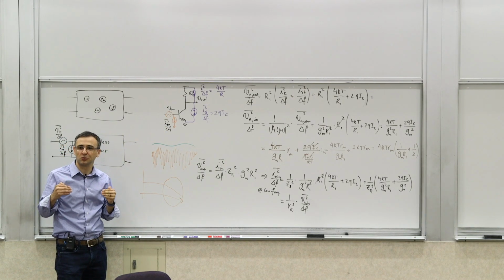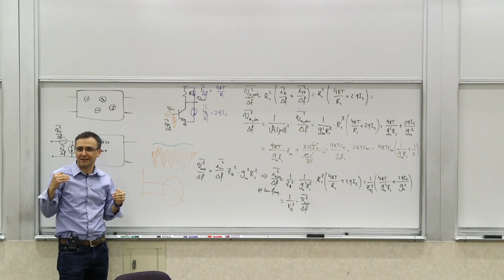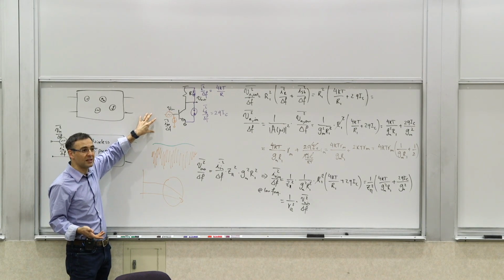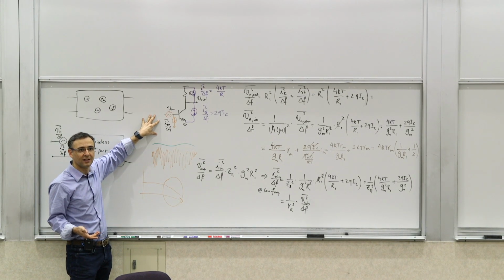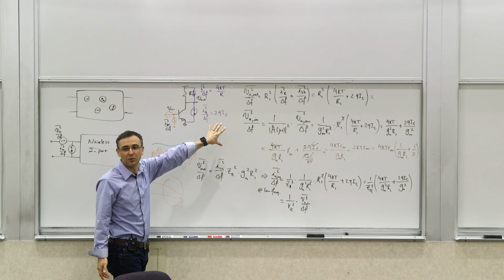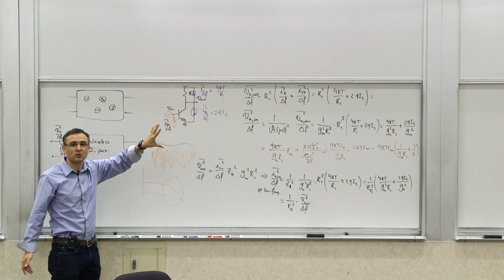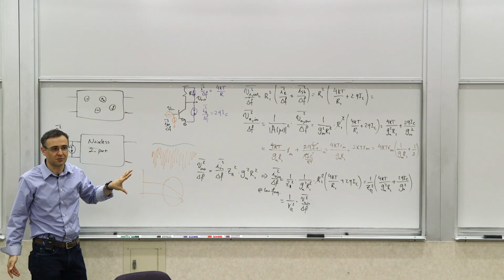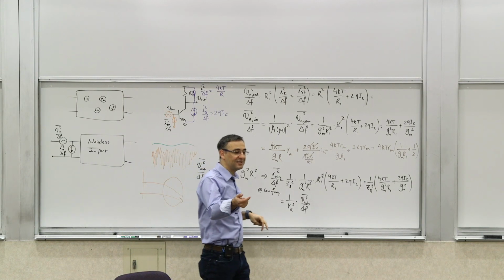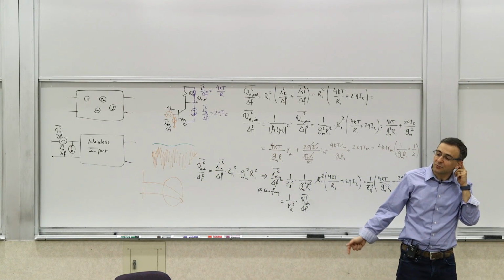And since the temperature is a measurable quantity, and Johnson noise has a direct relationship to it, it's a thermodynamics thing. So you know what your noise is, and then you do two measurements with a known noise source at the input, and you measure the excess noise at the output. It's called a Y factor measurement. And from those two measurements, you get two equations and two unknowns, and you solve them. It's called Y factor.